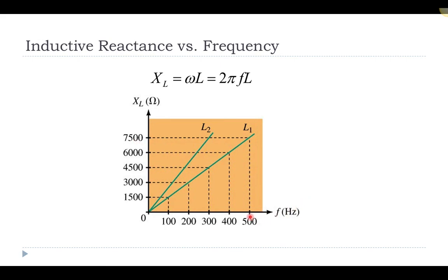So a lot of oscillation means that that inductor is really resisting the flow of electricity. And if you think about an inductor, remember, inductors, I put in parentheses, don't like change. And so they will do everything in their power to resist a lot of change. And so if you have a large frequency, that means your source is changing very quickly and very often, and an inductor is going to resist that. So there's going to be more resistance that way.